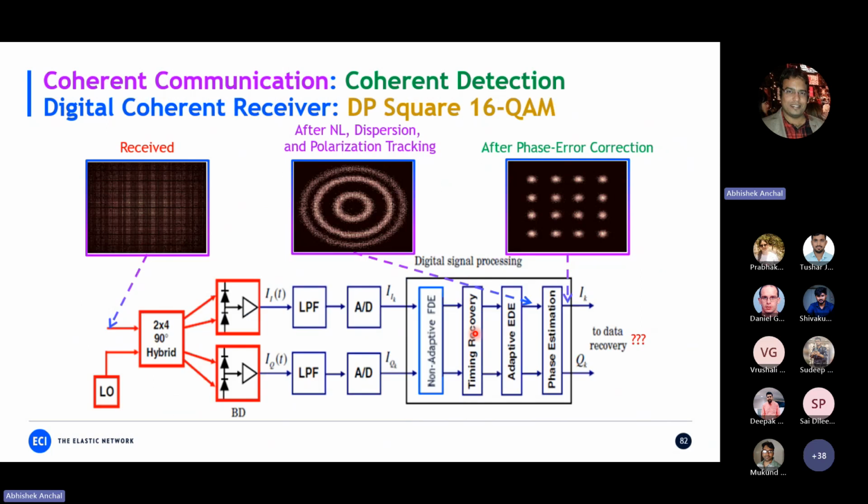Okay, so now I see how the symbol looks when it has passed through all the system at the receiver. So at the receiver end in the optical domain, we receive this constellation. We transmitted 16 QAM, and here we don't find whether it's 16. We don't see which QAM it is at all. This is the optical domain we find. We pass through the local oscillator, go through the optical quadrature front end.